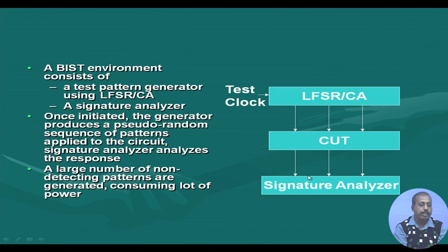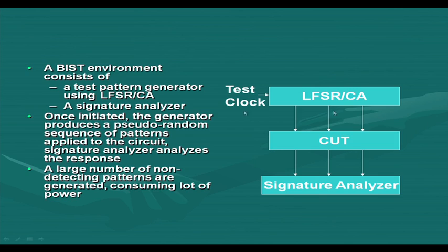That is the whole idea of this BIST based approach, but the difficulty is that maybe we apply the first pattern and it detects a number of faults. We apply the second pattern, and during fault simulation we have found that it does not detect any new fault. In the ATE based approach, we can choose not to apply the second pattern to the circuit, but here that facility is not there, because I cannot stop the LFSR from generating the second pattern. The second pattern will be generated and applied to the circuit, and it has no contribution in improving the fault coverage.